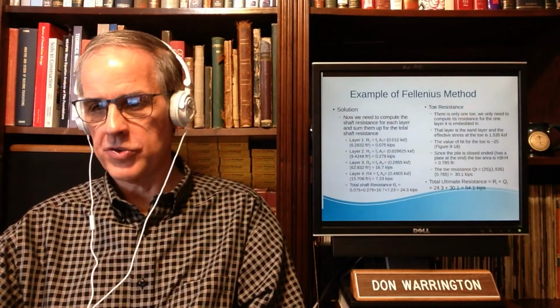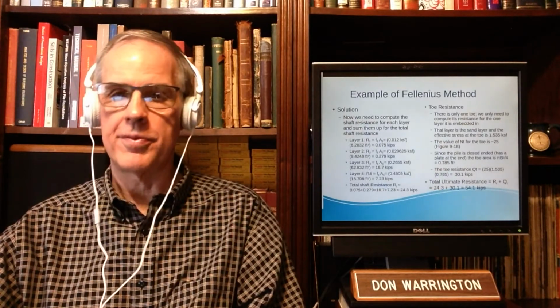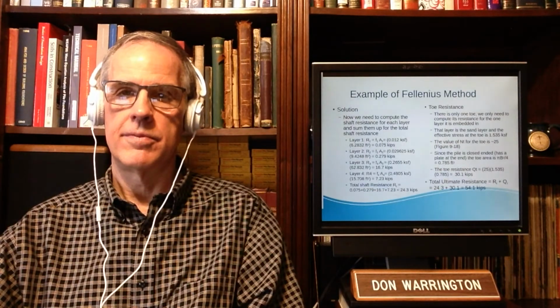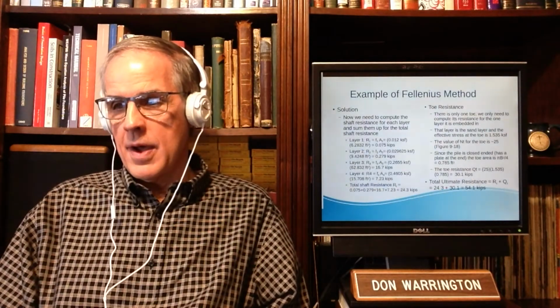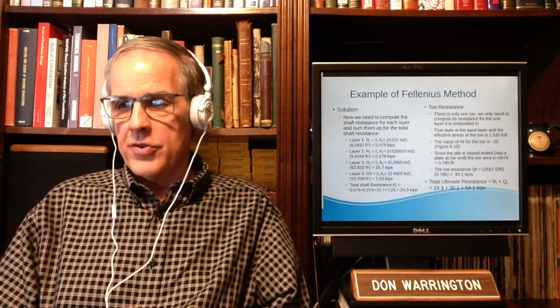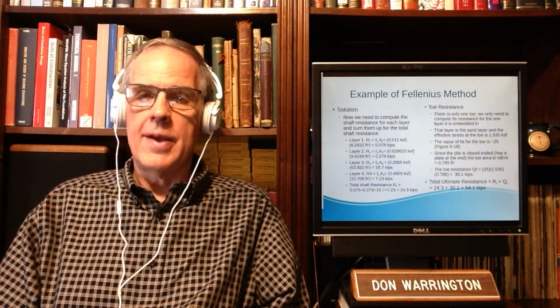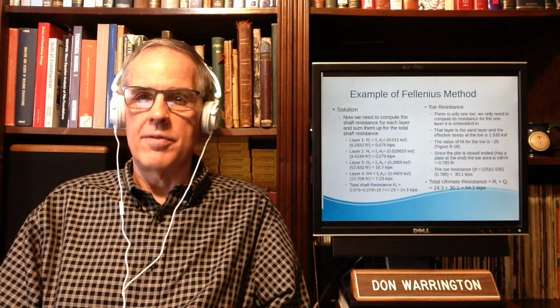And then I get a total shaft resistance, and just add all those up at 24.3 kips. That's ultimate. Toe resistance, well, there's only one toe. Now, sometimes I will see students when they're solving these problems give me a toe resistance for every layer. No.